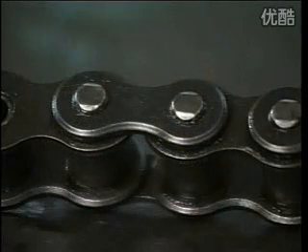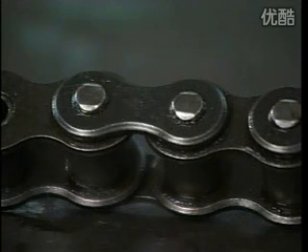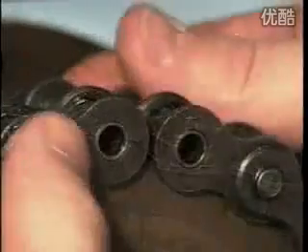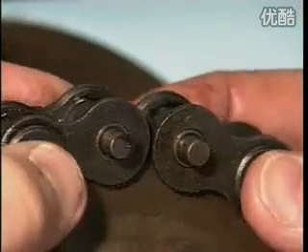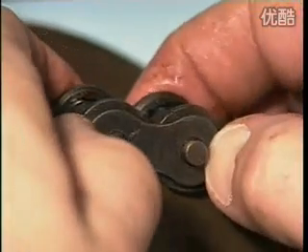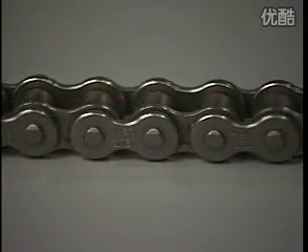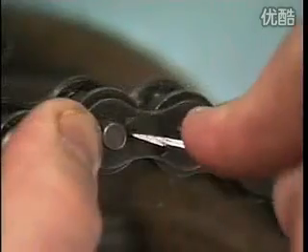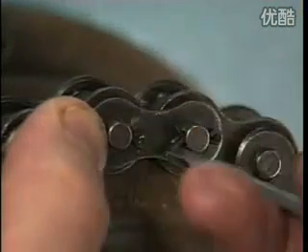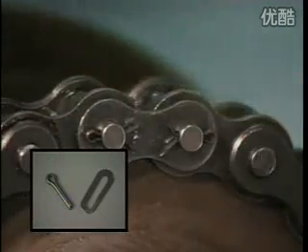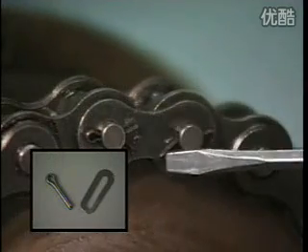The roller link and pin link are then joined and secured by either riveting the ends over the plate or by inserting cotter pins through holes in the ends of the chain pins. When the chain is installed, a connecting link or offset link is used to join the chain ends and make the chain continuous. The connecting link is used to make the chain endless with an even number of pitches. To provide for easy installation or removal, the connecting link is joined on a common link plate and held in place with a cotter pin or a spring clip.